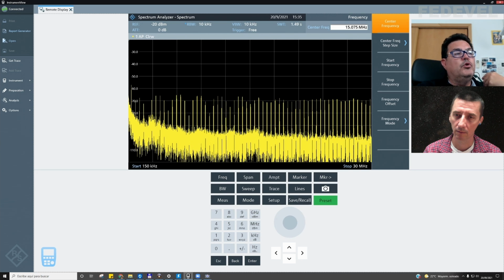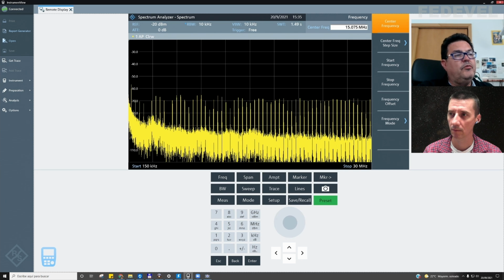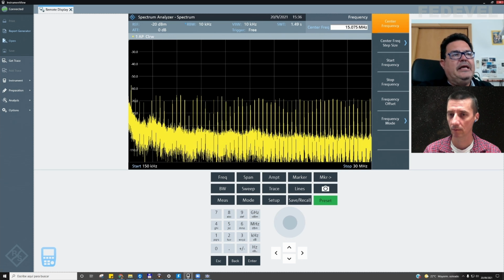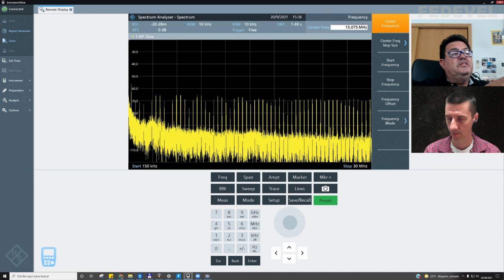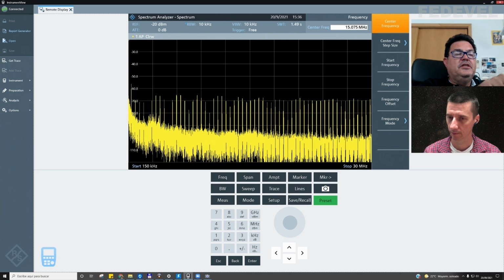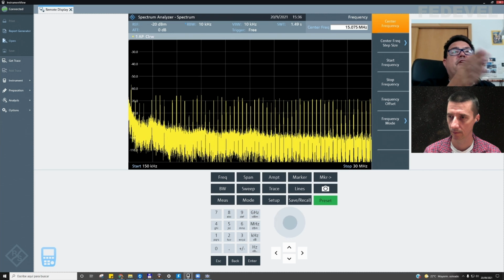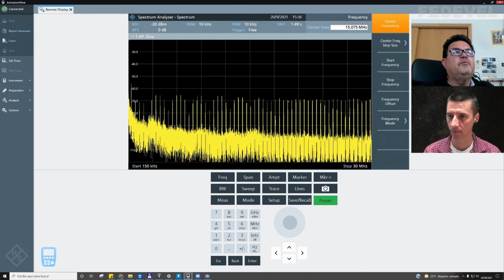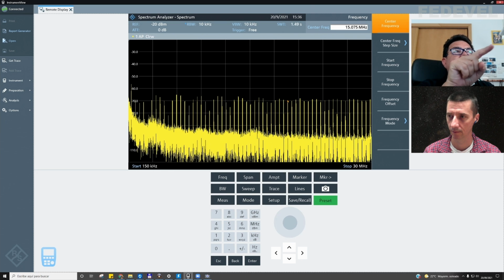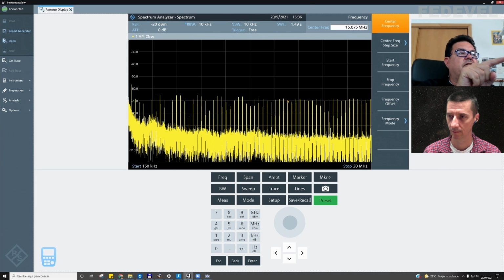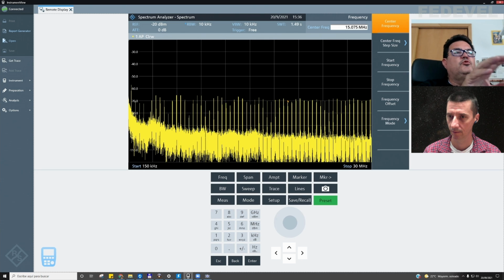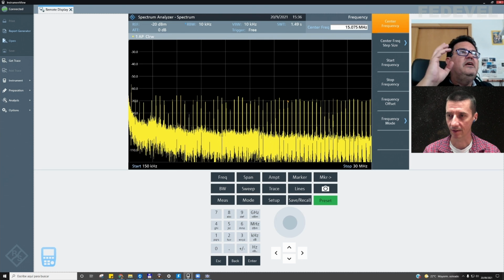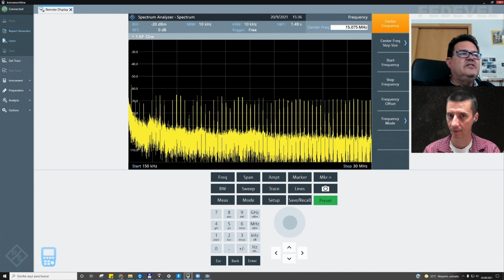But because you can import the file to your computer, you can manipulate it later, no? What you can see here is something that is very common in EMI, that the noise is periodic. So this is a very important clue to identify the origin of the problem, because you go from peak to peak, and you can find that the difference of frequencies is, I don't know, 200 kilohertz, and you say it's always the same. Yes, it's always the same.